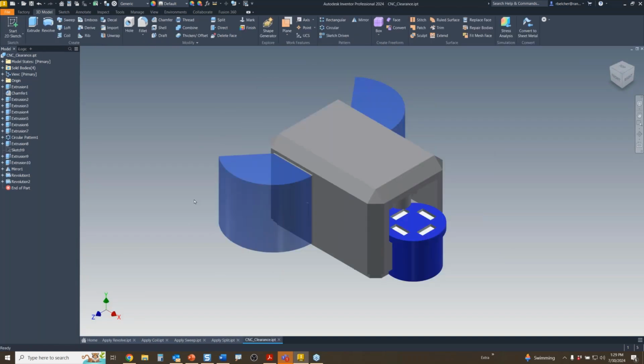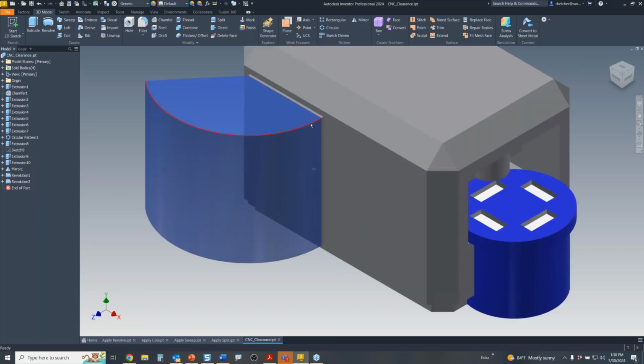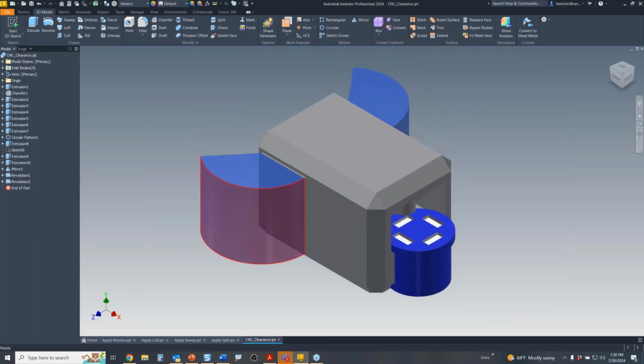Here you go. We have a CNC machine. This is something that came from my factory design training class, and it doesn't have to be used for factory design. It's the idea that every feature in your design has feature properties. So here's my CNC machine, and I've got these doors, and I modeled this secondary feature. So it's a multi-body feature, but I modeled this feature to show that these doors need to swing outwards. So if you're going to install this machine somewhere, you need to watch out for the clearance zones.